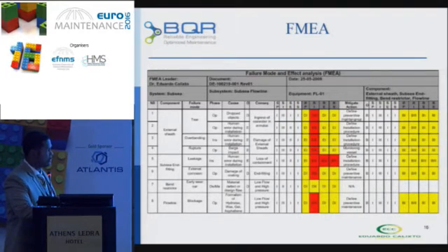This is one of the first analyses, the FMEA, failure mode analysis. Here you have a flow line system with different components, and we have failure modes, and the phase in which such failure modes happen. Here it is interesting that you can see that some causes of failure modes are triggered by human error: human error during installation, barge impact, and some failures in design. This type of equipment has high reliability unless some human error triggers or deteriorates it, and then it fails very early in the life cycle, and that's our concern here.